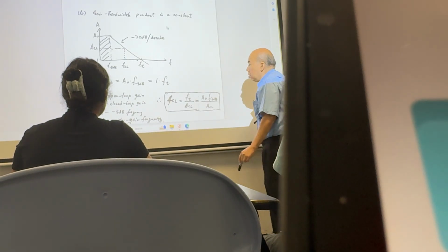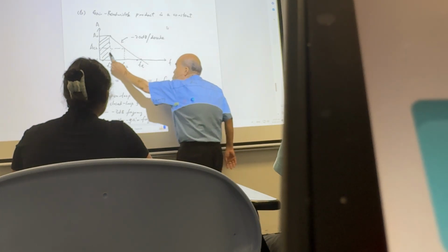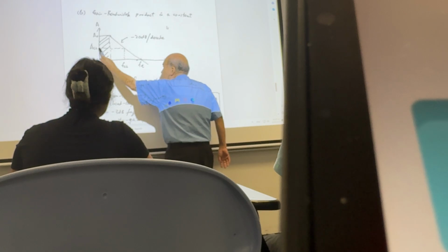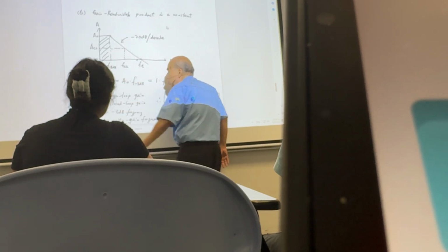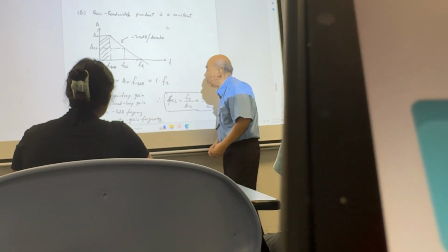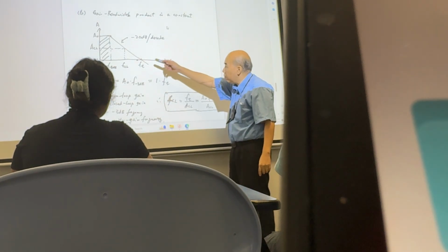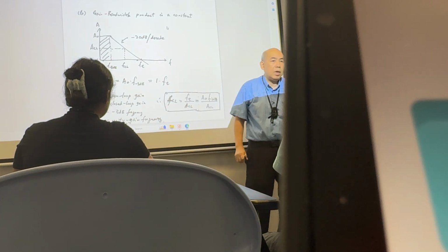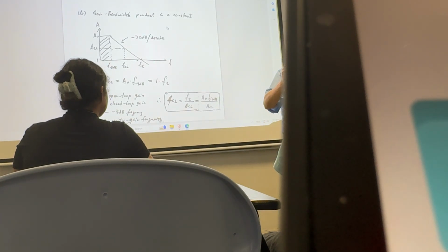And when you have the VDB point, the gain is A0 under high gain. Another area depends on your closed loop gain design. Because of this property, you can see that the roll-off characteristic for one pole is minus 20 dB per decade, meaning that the gain will drop 10 times with increasing the frequency by 1 decade. What is a decade? Decade means 10 times.